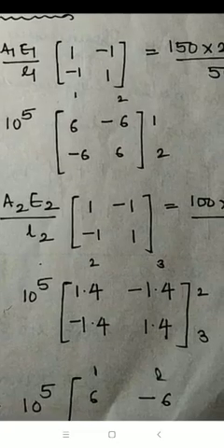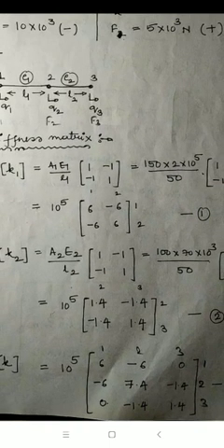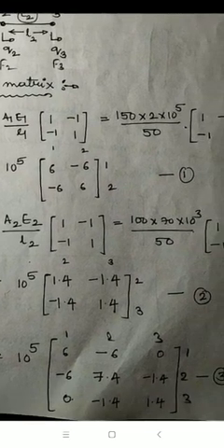So at the place of column 2, row 2, two values are coming. One is 6, another is 1.4. Both values we have to add. After adding, we get 7.4. See here in the global stiffness matrix, in the place of column 2, row 2, we are getting 7.4. Similarly, write down all the values of the matrix by applying the same procedure.